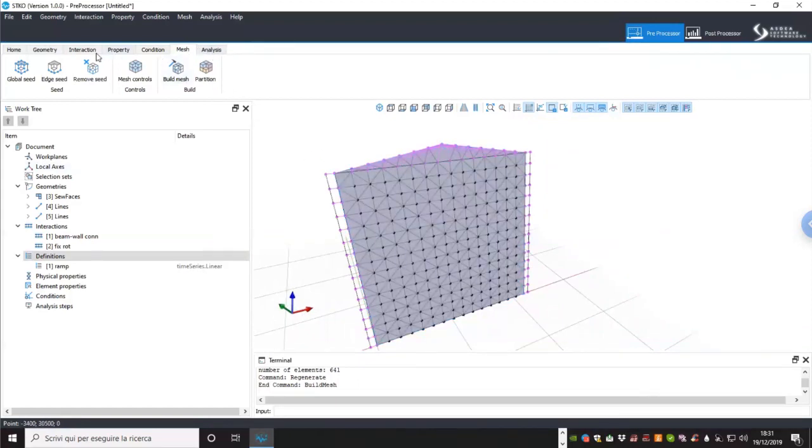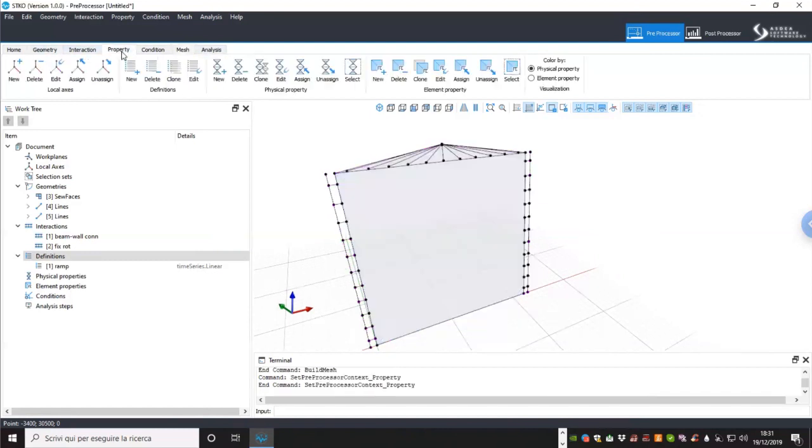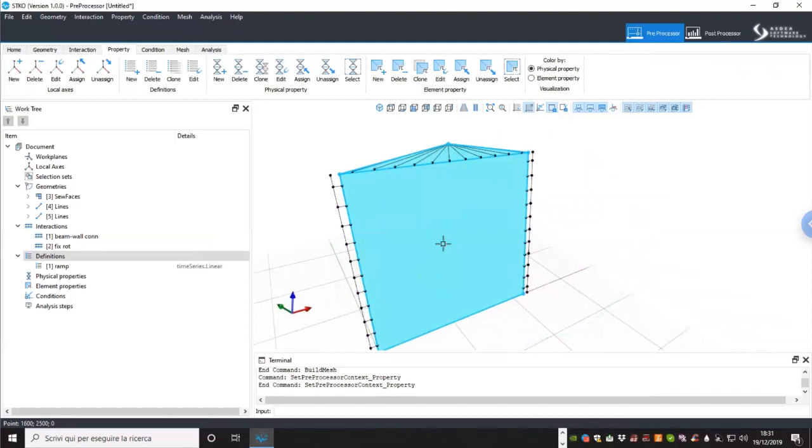Okay, let me go back to the property. In the same way, basically, we apply all the conditions. For example, even for people doing soil structure interaction, we also apply Lysmer-Kuhlemeyer absorbing boundary condition in this way. So you can define a boundary condition in a distributed way, and then STKO will do automatically the lumping. And so in OpenSees, instead of having a distributed load that you don't have, you will create just node-to-node connection.